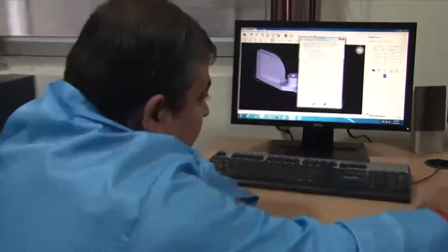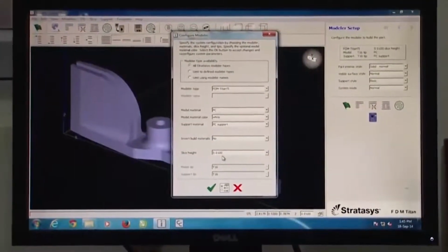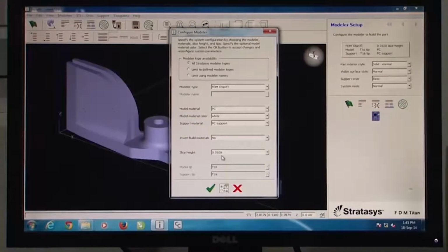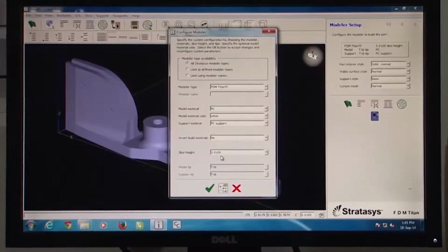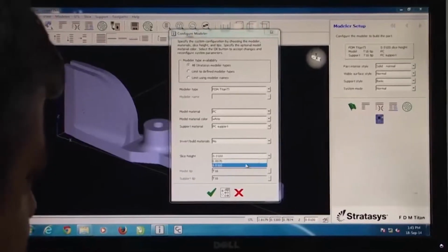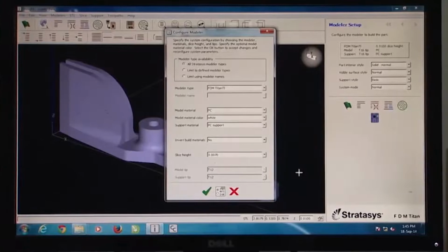And automatically, if you select this 0.01 option, the T16 nozzle is selected, which means that this would be able to handle and dispense the 250 microns layer. So T16 is probably a slightly thicker diameter nozzle in this particular case. If you had selected 0.007 as given earlier here, then you will automatically see that T12 is selected. That means a smaller orifice nozzle is selected in that particular case.